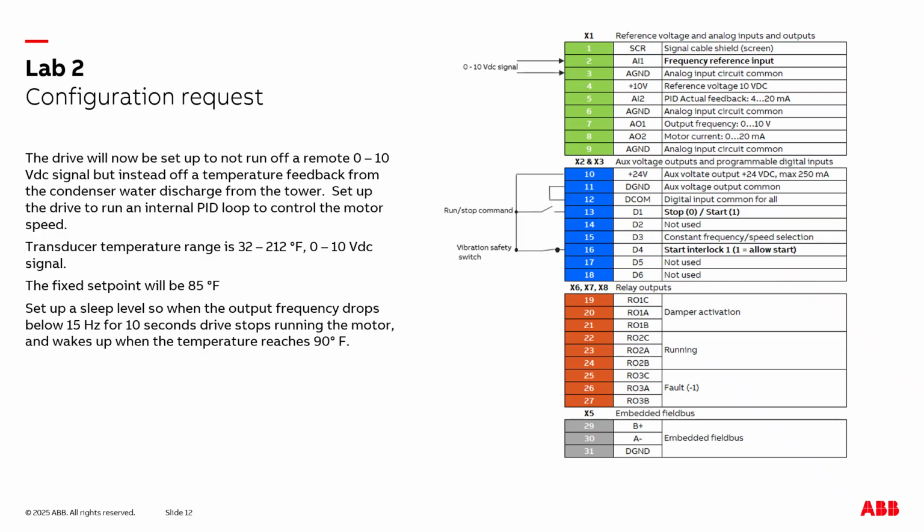And we're also being asked to set up a sleep function in the drive. This prevents the drive from running for prolonged periods of time at a very low output frequency. For this sleep function, if the drive's output frequency drops below 15 Hertz for at least 10 seconds, the drive will stop running the motor. And when the discharge water temperature or the feedback signal reaches 90 degrees Fahrenheit or greater, the drive will wake up out of sleep mode and start running the motor again.